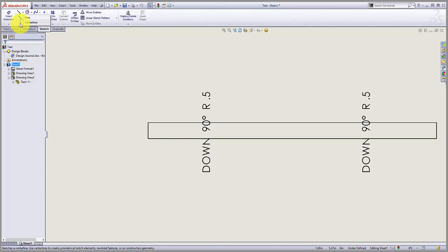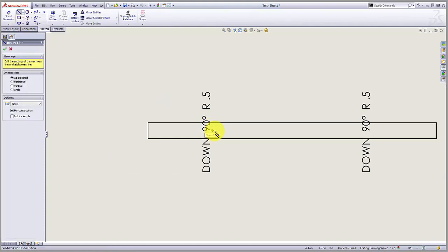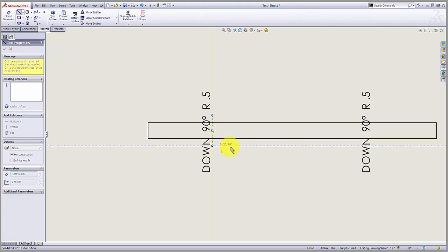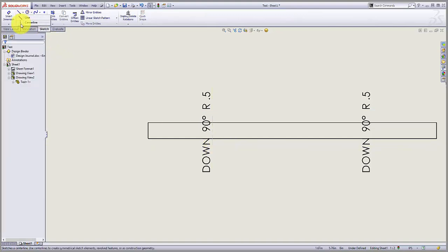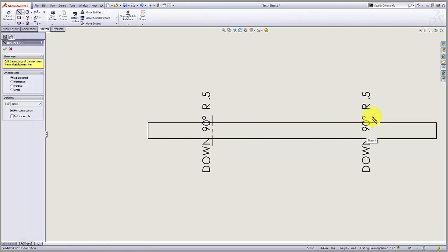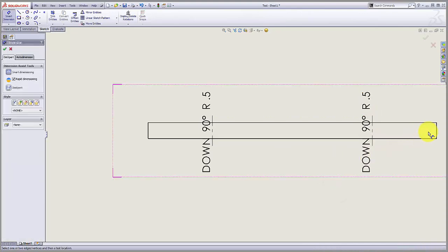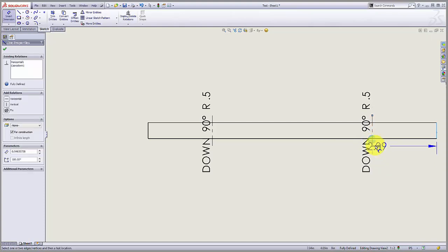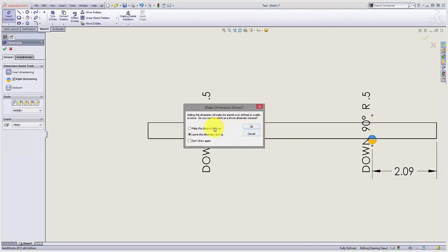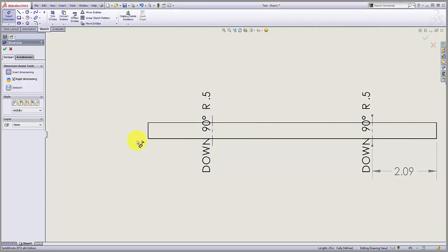And the simple solution is grab a center line, draw a sketch right on it. If you hit that center line, it will give you a coincident mark. So not too bad. You drop your center line on it, and now you can dimension your bend lines. So from here, if we want to throw dimensions on it, we can now dimension and dimension.